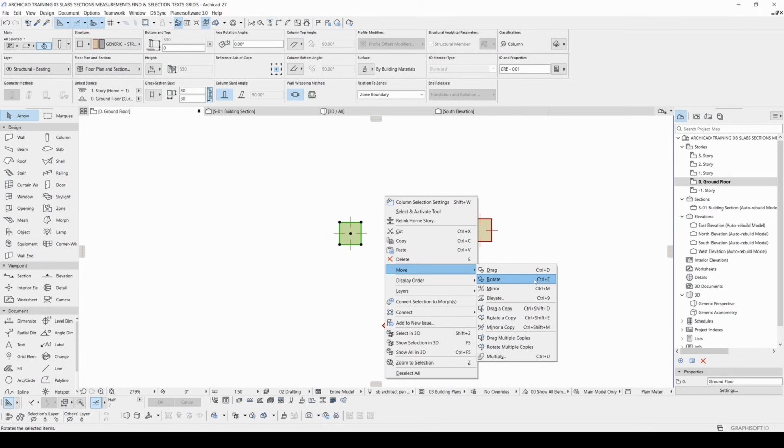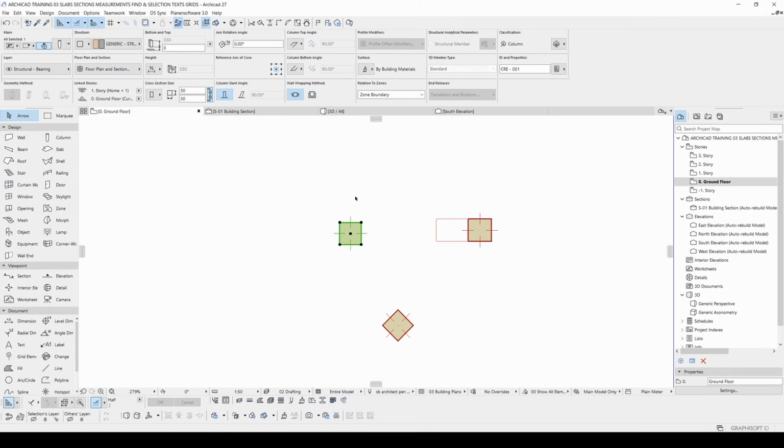I've changed it to Ctrl+E. Just like this. First, we will hit Ctrl+E or any shortcut you determine. After that, you will select your rotating point. For instance, this point. You will click your reference point line such as this, and you can rotate. And lastly, you can finish.